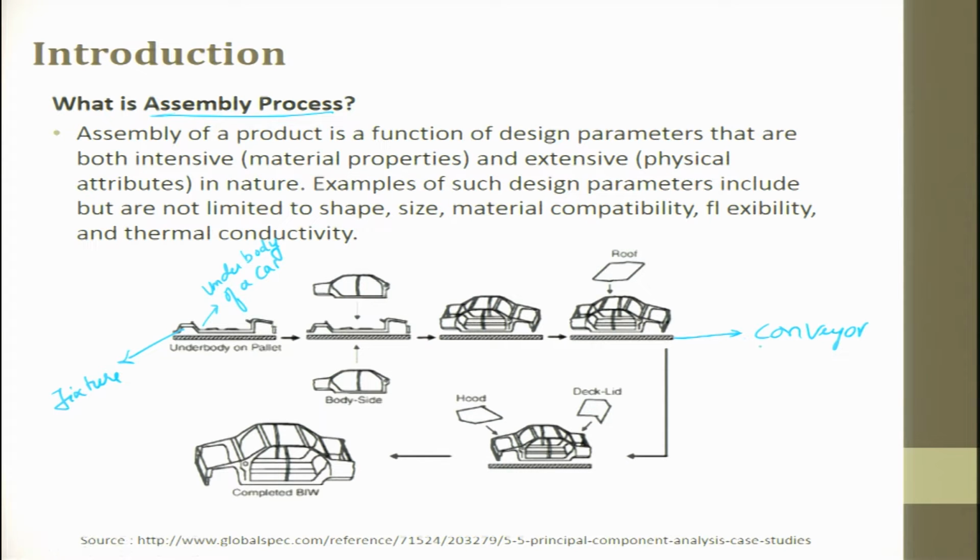You can do two things, continuous feeding, or you can also have discrete conveyor moving speeds. So, when I say discrete, it comes and stands at a station and it stays in that station for a limited time and then it starts moving to the next one. So, when you do this, the entire cycle time of all these stations has to be balanced, both in terms of inventory and second in terms of the operations that are to be done.